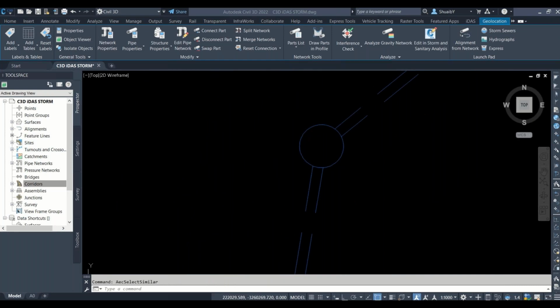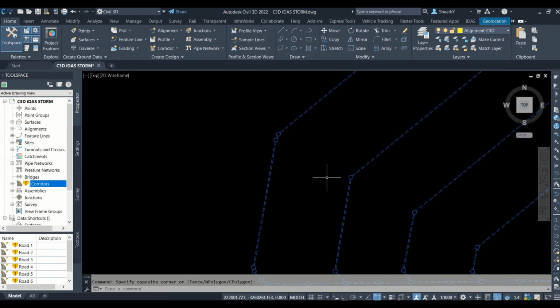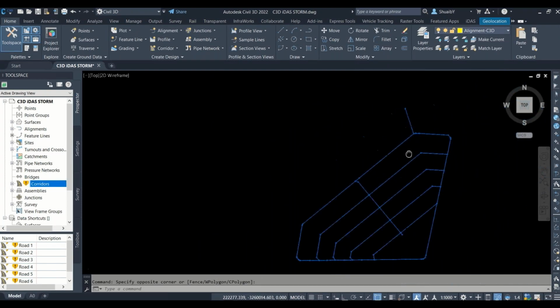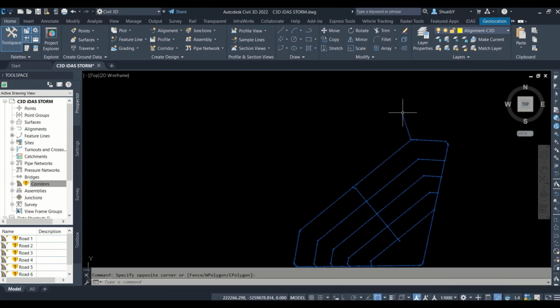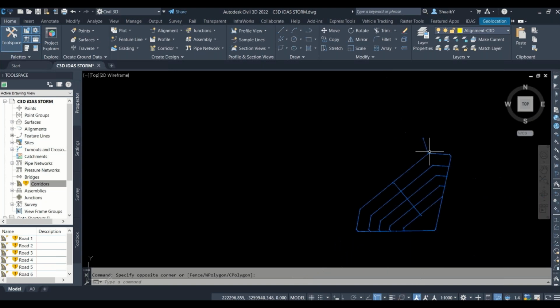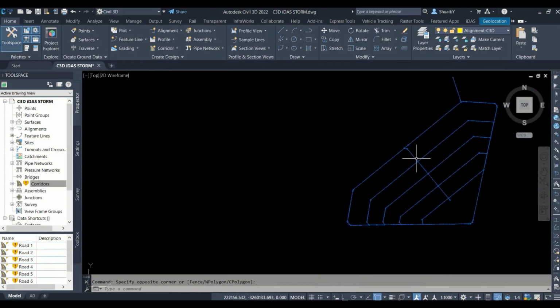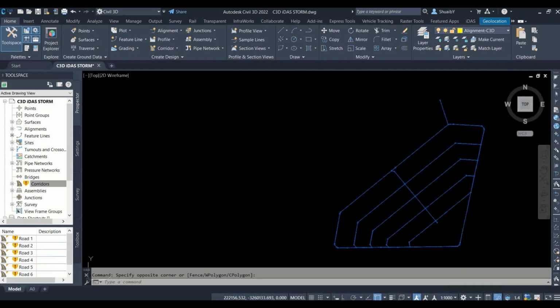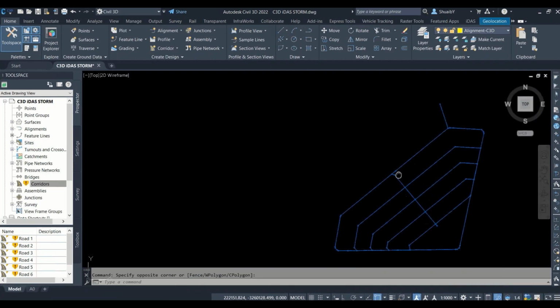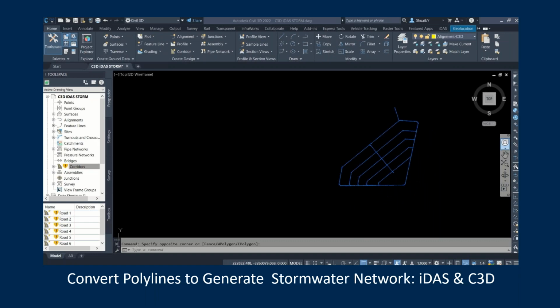And then I can zoom out and you will be able to see the actual extent of the pipe network, and that is the result. Of course, we can have our outfall there. We can go and edit a lot of the layouts. For example, at those center points, I might rather change them to inlets, but you will see that in a bit. All right, so that is the pipe network layout done in a few clicks, very, very quickly.